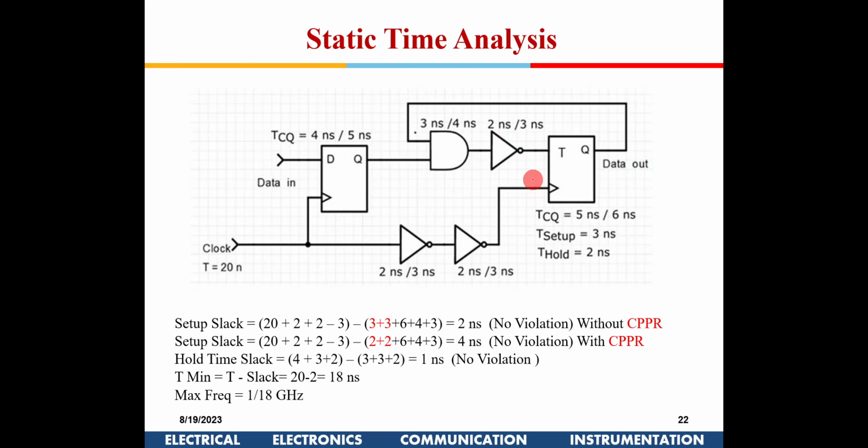So once this clock is triggered here, data will change here, and that data needs to be settled here, right? And here, what is the delay here? So there are two data paths. Okay, so this is one data path coming here. The second data path is through its own feedback path. So here it is 6. 6 plus 4 plus 3, that is 13.